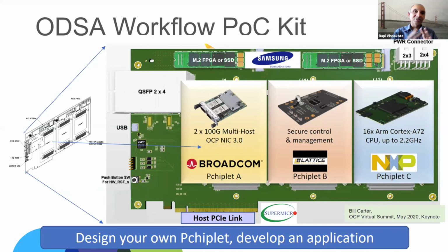There's an engineer from Cisco who came up with this idea of, why don't I give you a system level design which allows you to explore chiplet architectures? So I'm going to give you a baseboard which mimics a substrate, and that baseboard provides power, test, and management interfaces to daughter cards that act as chiplets. We call the daughter cards PCB chiplets.